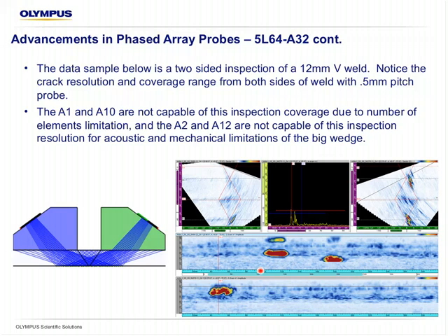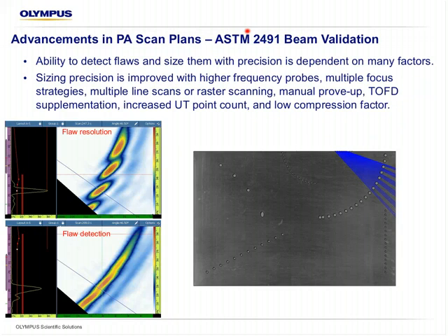This two-sided coverage uses the same number of focal laws as a traditional S-scan, but much more coverage. If we increase the angular resolution to 0.5, we will use the same number as 2 groups on each side of the weld, but it's a much more efficient inspection. And most importantly, we're not backing the probe up for coverage, and this single setup with a long enough TCG can be adapted for use on other weld bevels by just adjusting the UT parameters.